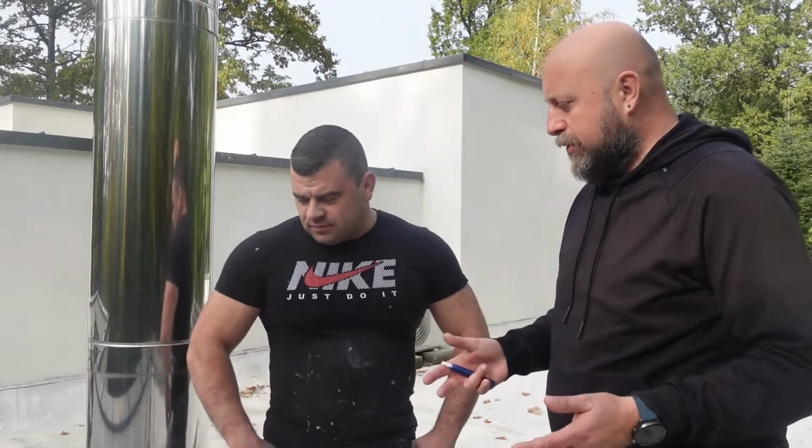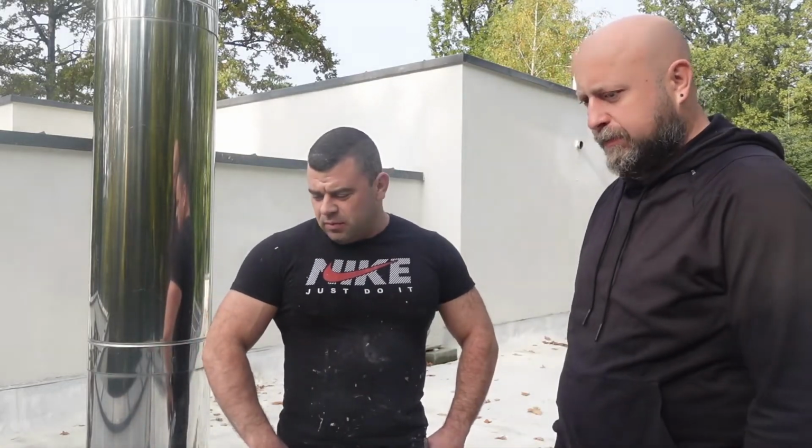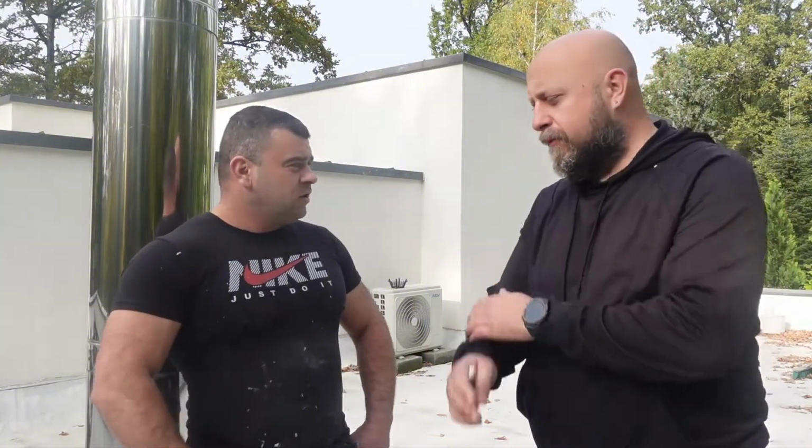So yes, what do we have now on this roof structure? We have applied 2 layers of paint, an underlay felt and then the main surface felt laid crosswise. Crosswise, yes, it is important. Next we have applied a reflective agent, KAWA.